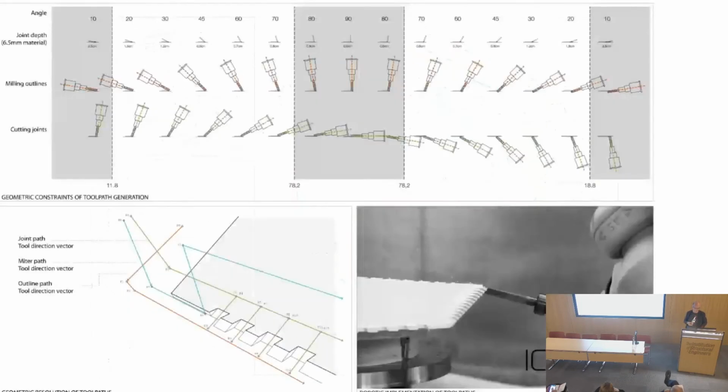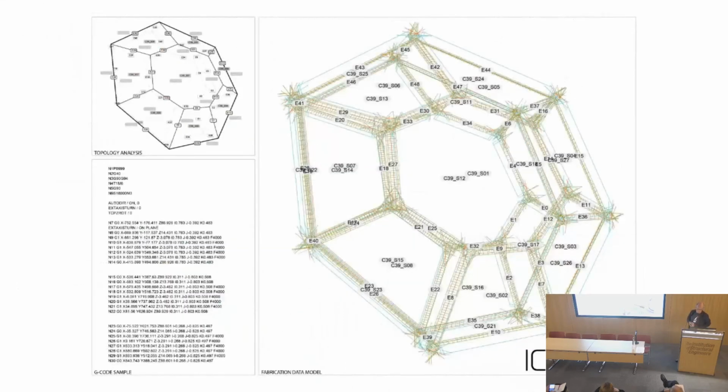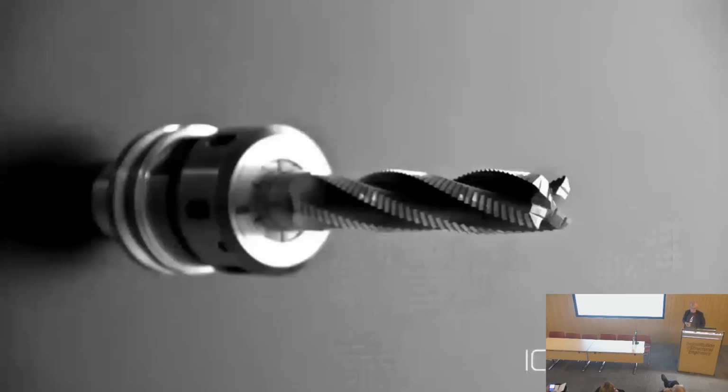These are their slides. But the key thing is they're thinking about how you might manipulate that material and how you might control the path of a tool to cut that material and shape it. These are called tool paths. What happens on this slide back here is that you process your geometry through various bits of software that you write, and it gives you G-code, which is basically instructions for how the machine should move and how it should cut the material.